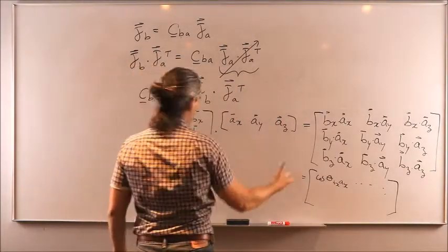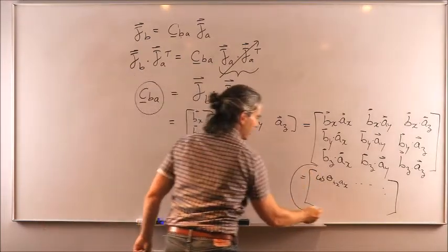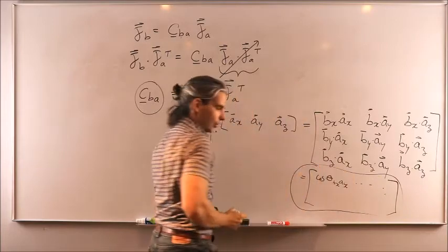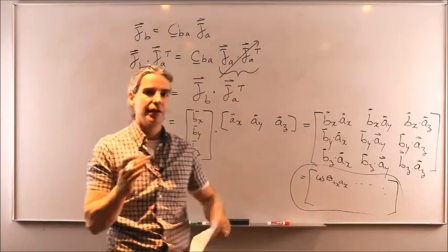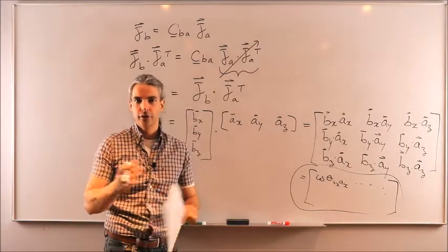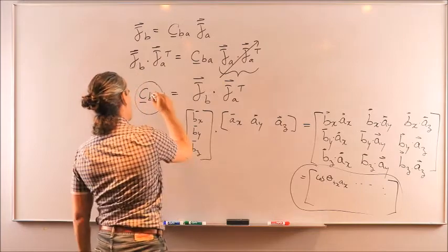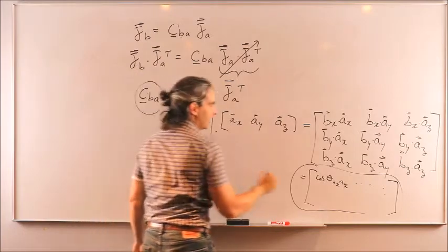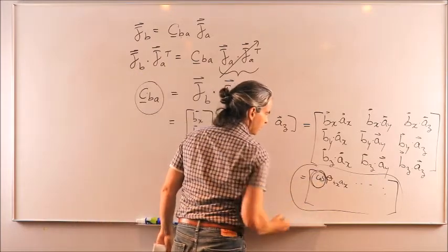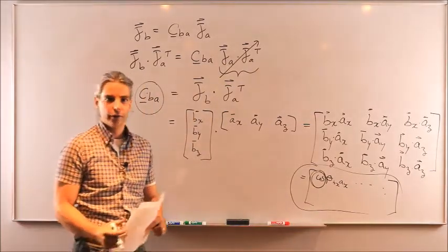So that's what it is. So rotation matrix, C_BA, is just a 3 by 3 matrix that can be calculated by taking the cos of the various angles that are defining the orientation of all unit vectors of the frames. And this is why people call a rotation matrix a direction cosine matrix, because of all the cos function involved in the calculation of it.